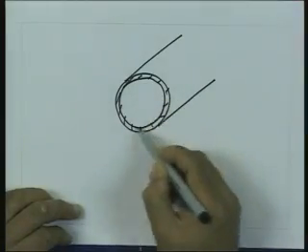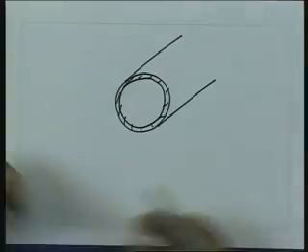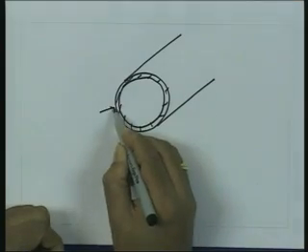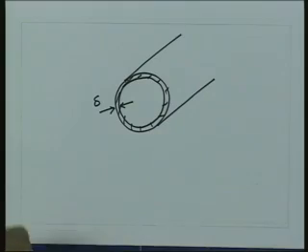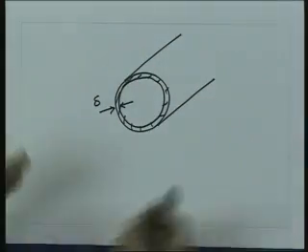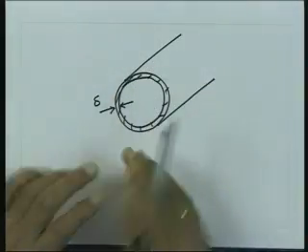So, this region, though you have conductor here, is not really contributing to the flow of current, because the current is confined to this, where the thickness is delta, typically of the order of a few tens of microns. So, even if you make this conductor hollow, the propagation of energy along it will not be affected, because this layer still remains intact.